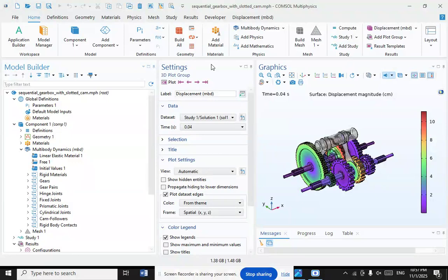In a transmission for transverse engine vehicles, for example front-wheel drive cars, there are usually only two shafts, input and countershaft, sometimes called input and output. The input shaft runs the whole length of the gearbox and there is no separate input pinion. These transmissions also have an integral differential unit which is connected via a pinion gear at the end of the